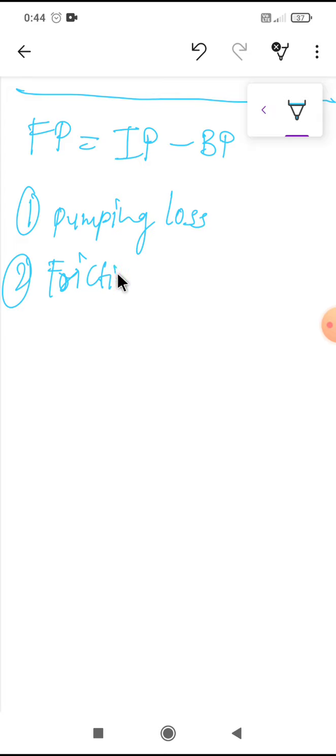During the inlet and exhaust strokes, gaseous pressure on the piston is generated on its underside during the inlet and on its upper side during the exhaust stroke. Hence, during both strokes, the piston must be moved against a gaseous pressure, and this is called pumping loss.